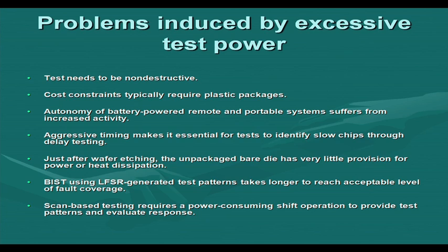We need to identify the slow chips. If something is not able to operate at the desired high frequency, then it needs to be separated out. So, this aggressive timing requires that slow chips be separated through delay testing. Delay testing has to be done at the operating frequency. You cannot say that it will be done at a lower frequency.